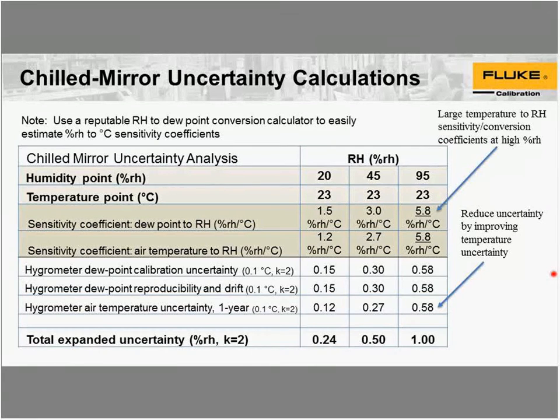So for example, he uses an S point to check his thermometer. Is there anything like that we could use to check humidity? Nothing's coming up. Someone mentioned the salt earlier. Possibly that could be kind of like a point to check your sensors, but in our laboratory we just have a humidity sensor that we keep as a check standard, and we check against the reference. So a fallback method is to have another reference to check it against.